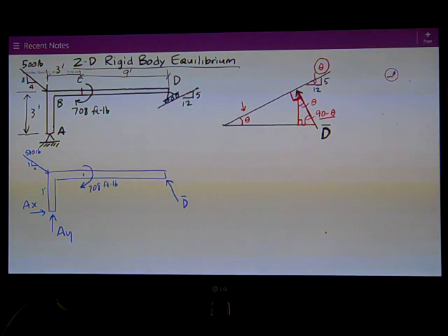So what I can say is that if I have a force that's perpendicular to a 12-5 slope, what I've got is a 5-12 slope like that for the force itself. So I want to put that information over here on the force, which is 12 and 5. So of course that's a 12, 5, 13. So I'm ready really now to get everything in Cartesian format.